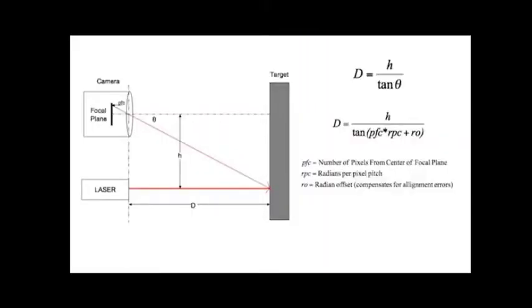As you can see, the laser dot moves closer to the center of the camera frame as the target moves farther away. This information is important because we can use it combined with the triangulation LiDAR range measurement technique to determine how far away a point is from the LiDAR. Triangulation LiDAR range measurement technique sounds complicated, but it is just simple geometric calculations.